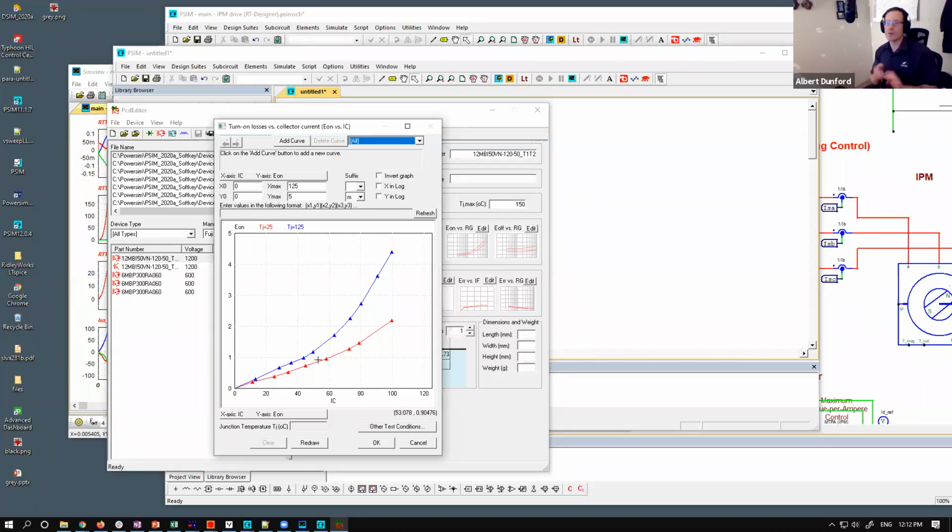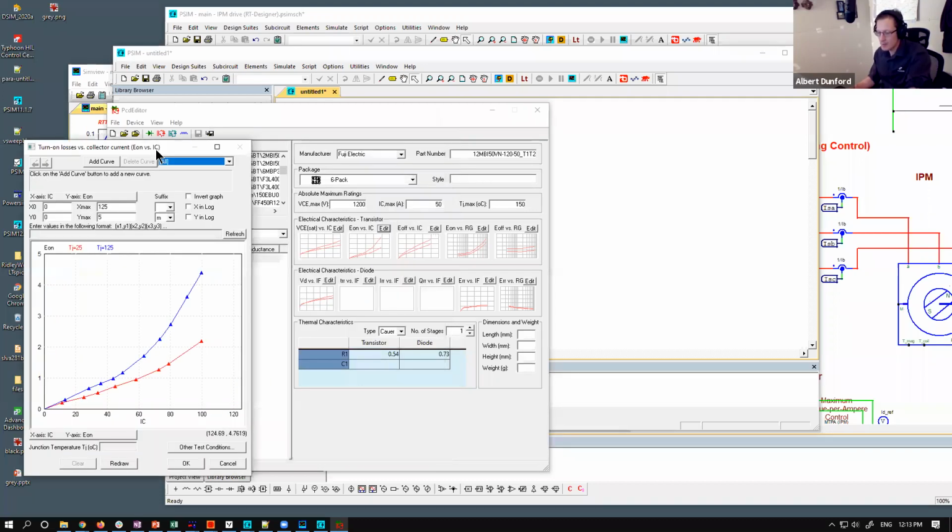So we're not integrating the voltage and current. So it's an ideal transition, so we can end up with simulations that will happen in a reasonable period of time, nice and fast. And then we can start comparing this IGBT versus the silicon carbide device if we wanted to look at that justification, or look at how hot our motor gets during certain drive cycles or during acceleration, or all those sorts of things.